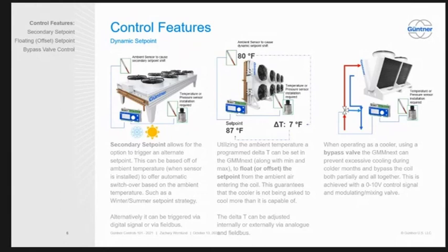The only time I've ever seen that is if you're dealing with a cascade, and you're basically just using part of the adiabatic as a desuperheater. That's the only time I've ever seen that. Yeah, I'll be honest, I haven't seen it used too much, but there are a lot of our customers, I take that back, there are a lot of our customers that do use it. Probably a lot of dry cooler stuff. It could be used on a dry cooler as long as the temperature pressure sensor is installed. Okay. So it's just to bypass the unit if need be.